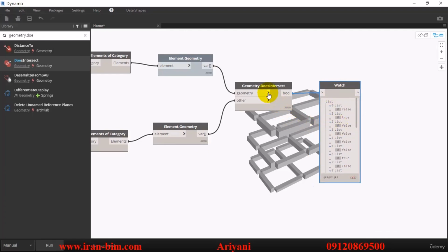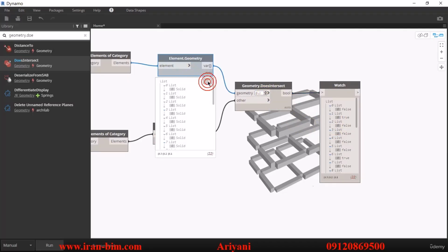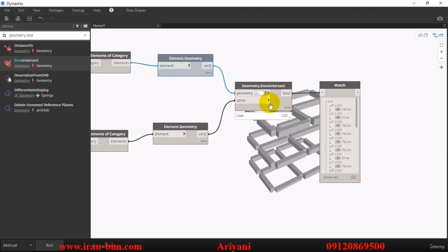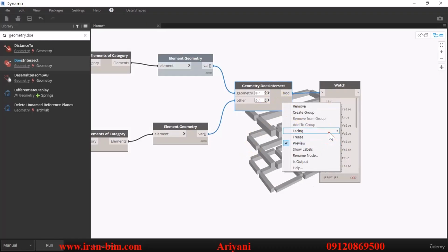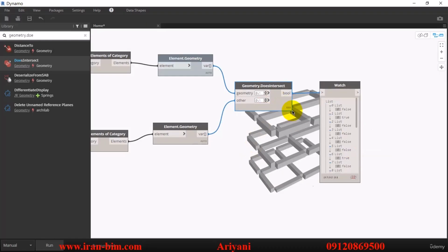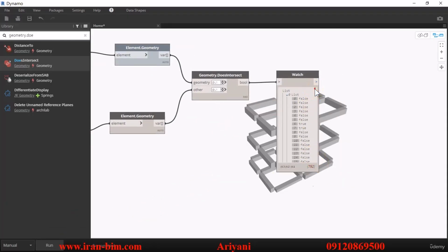So now in order to see these better, I'll use this and put it on use levels, put it on level 1 because that's where we want to see it. And then under the other option, put it on level 1 as well. And then I'll select the cross product option, which checks all of the items. Then run, and now it's checked 792 items.